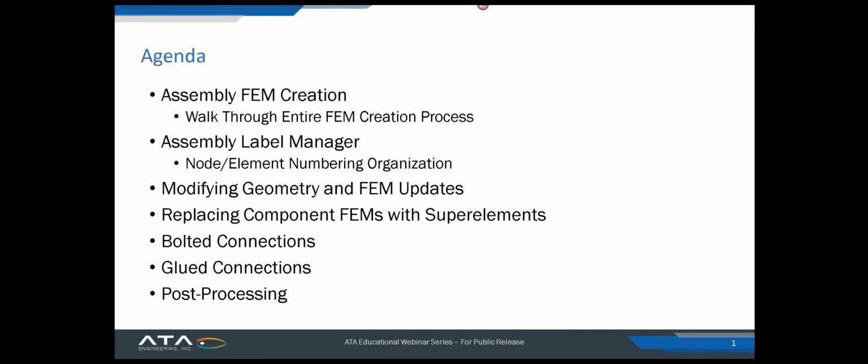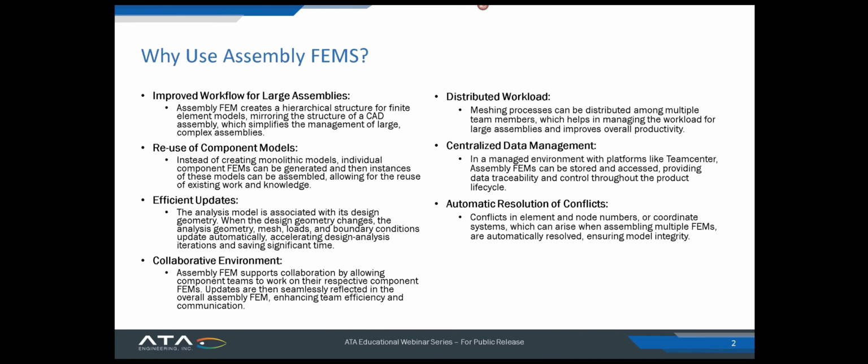So mainly going to talk about using the bolted connection tool as well as glued connections. And then finally, we'll talk a little bit about post-processing. All right, so why use assembly FEMs? There are some really critical reasons that are listed on this slide.